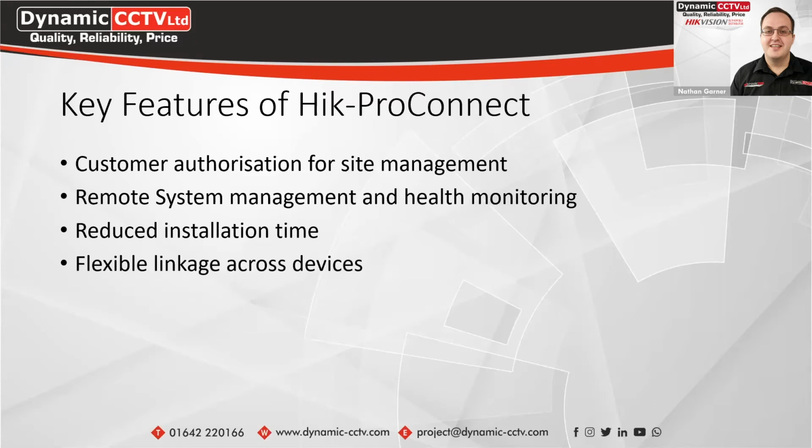So with HikPro Connect, you can use flexible linkage across devices. As I said earlier, for example, if you had a PTZ on site, which is also added to HikPro Connect for the site, when a detector goes off and is triggered on the AX Pro, that can send the PTZ to a preset position. So if you had a door contact on a front door that was triggered as an alarm, you could have a PTZ in the car park, for example, spin round to that front door, and that can also start recording or anything like that through HikPro Connect.